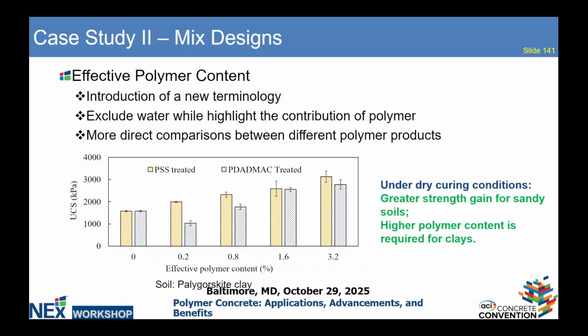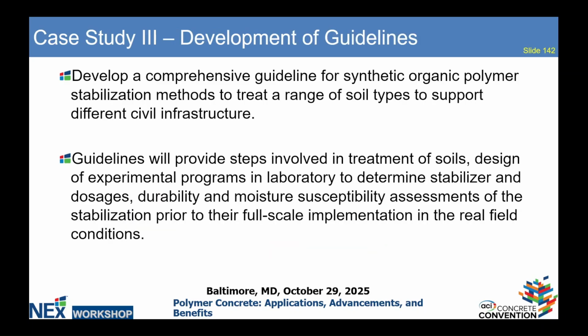And then also we need more polymers because clay is a mineral that is relatively reactive compared to sand. So that means it's more difficult for the polymers to penetrate and mix well with the soil particles. Eventually that causes a lot of challenges in the mixing, and then it might show in the strength as well.